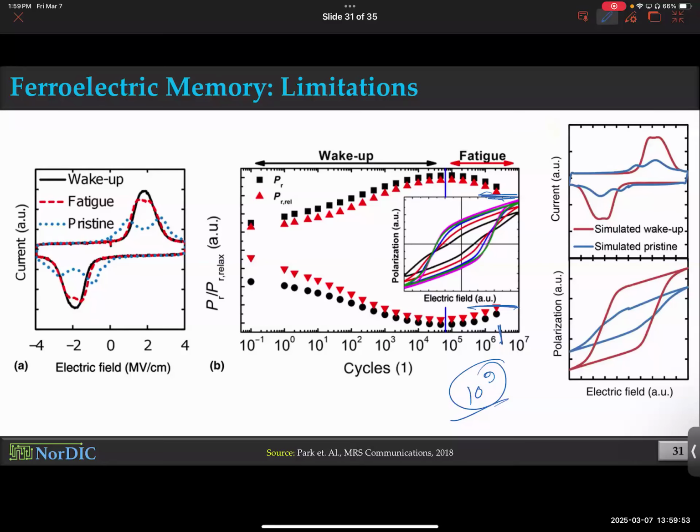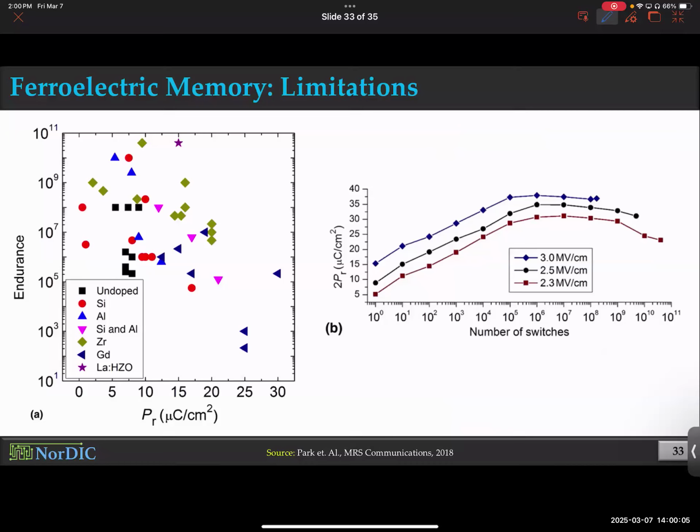Yeah, that's a good question. It will probably not decrease seriously. It will probably saturate, but for some memories, and I'm going to show you in the next slide, it depends on what type of ferroelectric material you're using. Typically people are trying to dope the conventional ferroelectric material with different elements, including zirconium and silicon. These are the two things that I personally worked with. Apparently they make the ferroelectrics better, and they also help with the fatigue situation. So it's possible to make it saturate and not degrade any further, but if you just deal with any raw ferroelectric, there are certain materials which will basically diminish.